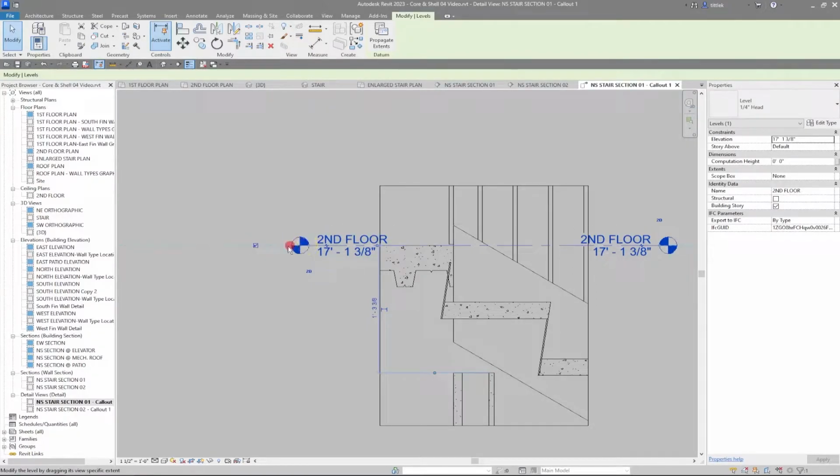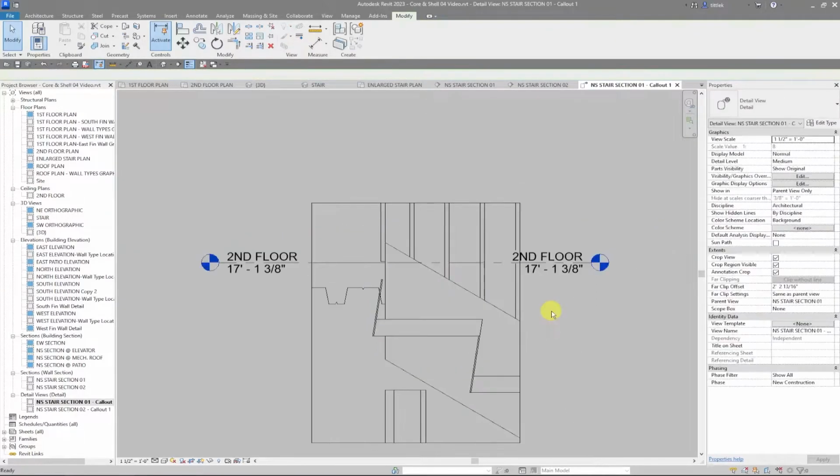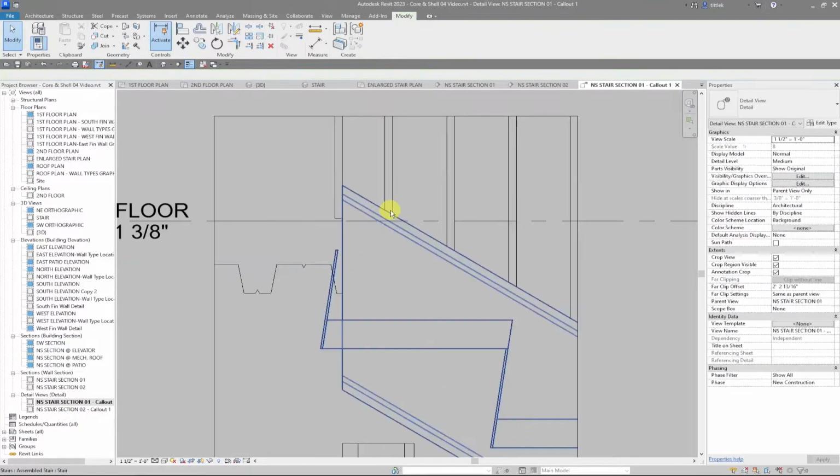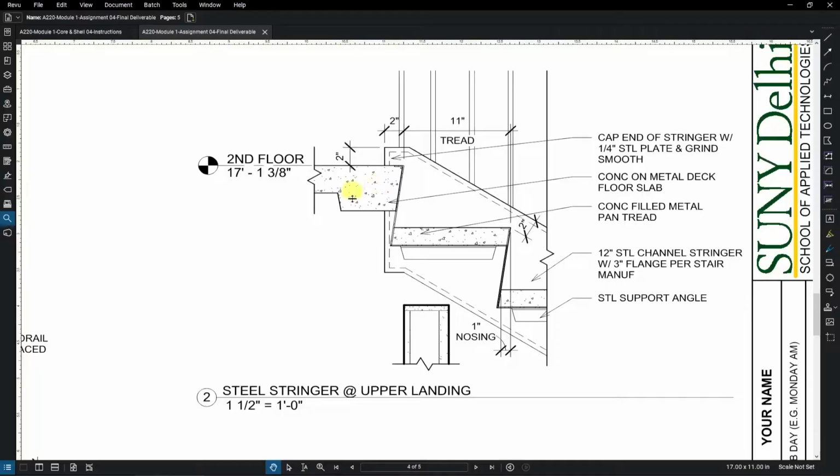I can pull it away from the drawing just a little bit, and then I can select it again and turn off the symbol on that side. So I'm going to start up here where the slab essentially at the top of the stair needs to turn into another nosing. So we can't make this detail happen in 3 dimensions. We have to only do it in 2 dimensions.